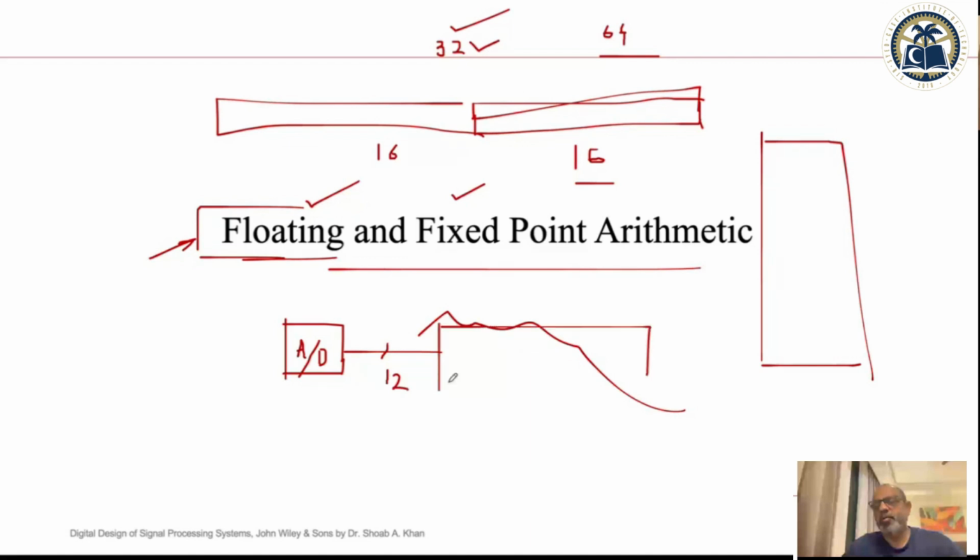Though here all your computations are at high precision, once you are going to convert it back, playing it on a speaker or displaying it on a screen, you cannot do 64-bit. There is almost no D to A converter which can convert 64-bit numbers. Usually they don't support these many levels. So there is a restriction.